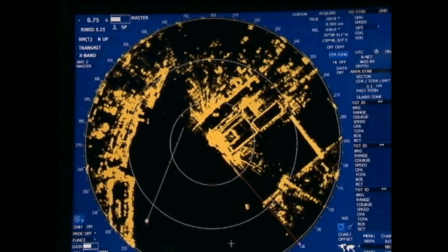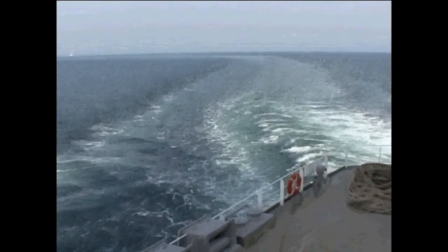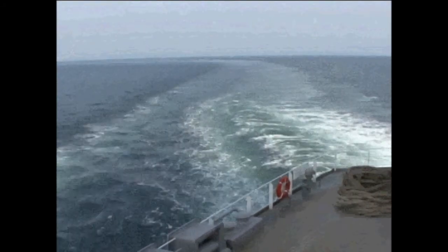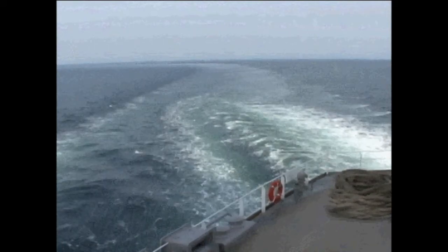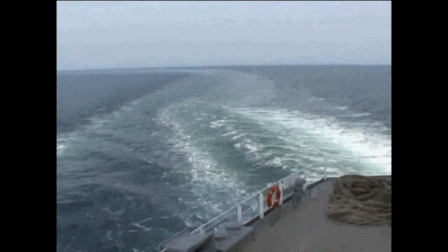When a new target has been picked up, it may take 3 minutes or more for its vector to reach a prescribed accuracy. Also, if either the target vessel or own ship has changed course, it may take a few seconds for the vector to be rendered accurately.